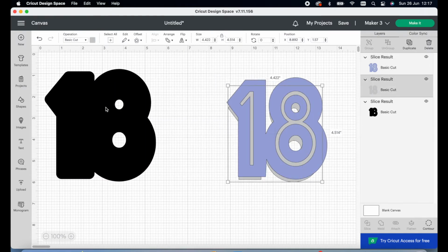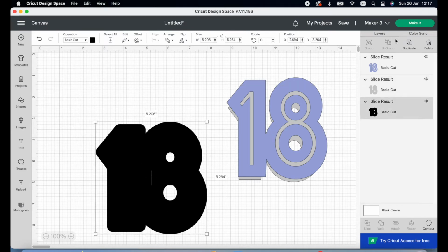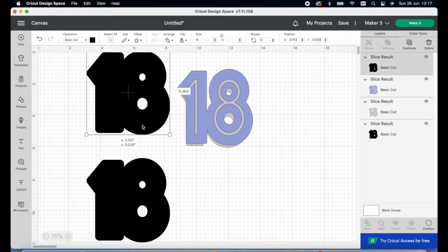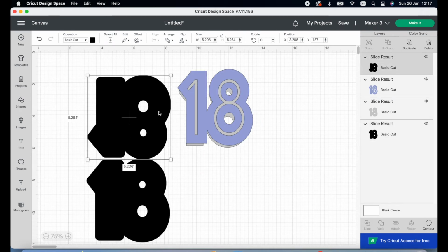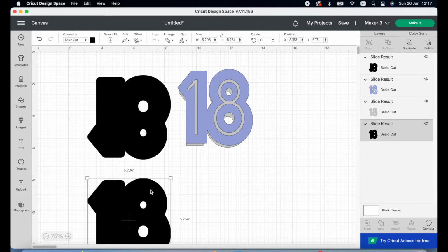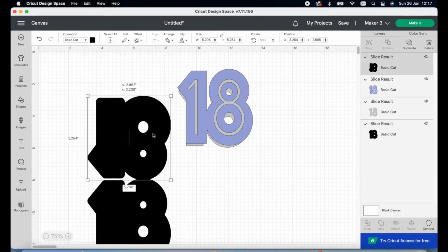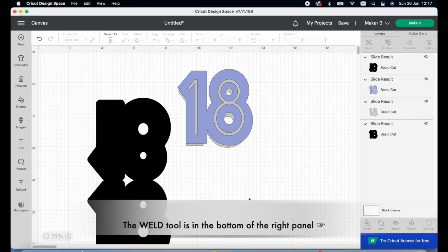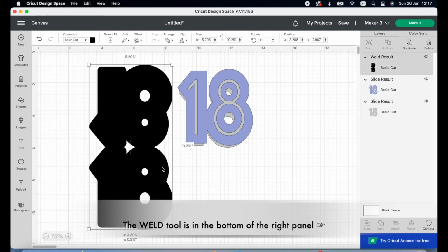So I need to duplicate my biggest outline, then go to the top panel and choose Flip and Horizontal. And then I need to overlap them by about 1/8 of an inch. And then I need to highlight both pieces, go to the top bar and choose Align and Align left or right. This will make sure they're accurately aligned, and then we can weld them together.